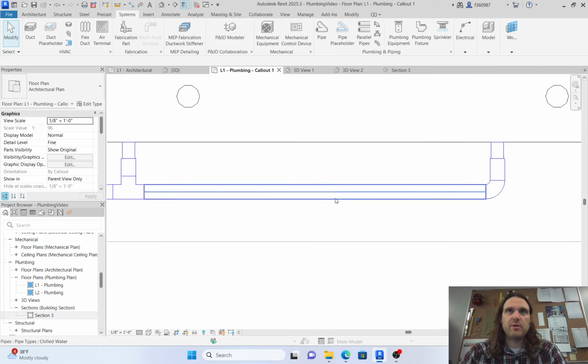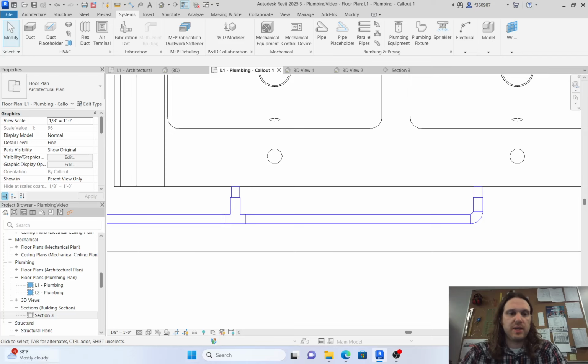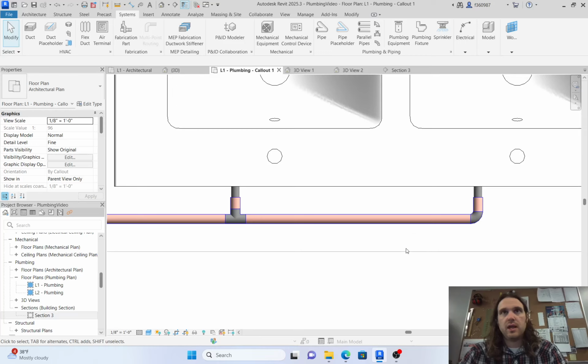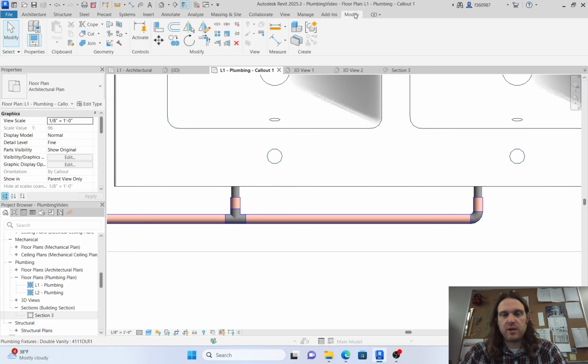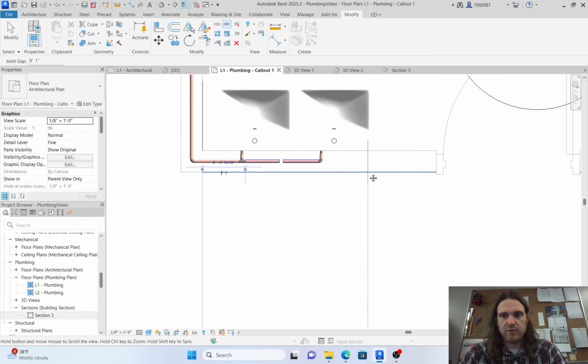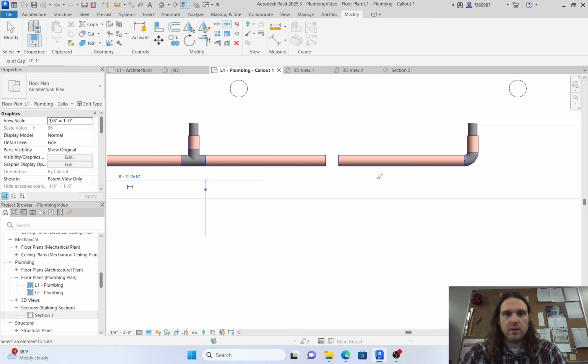And actually, I think what makes the most sense for us getting our water down into the basement, let's do wireframe. What makes the most sense for getting our water down into the basement, maybe it is harder to see in the video, is we can put a split in this pipe, and this will be our cold water supply. So I'm going to actually put a split in the pipe right here. There's no other fixtures in the bathroom. And then we're going to go like this, actually.